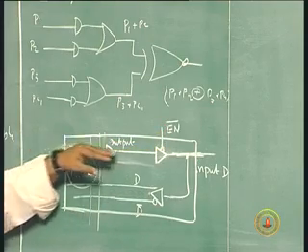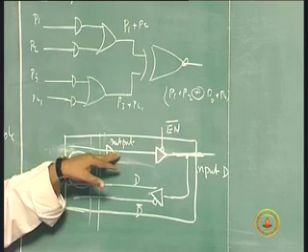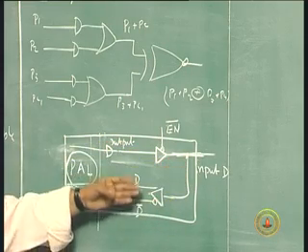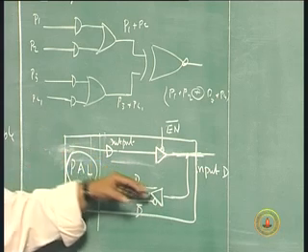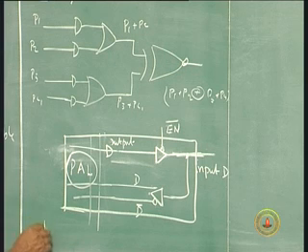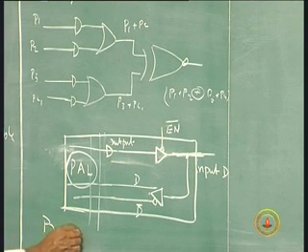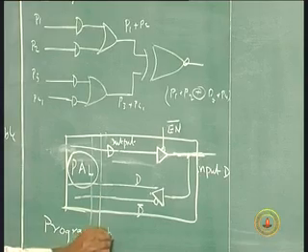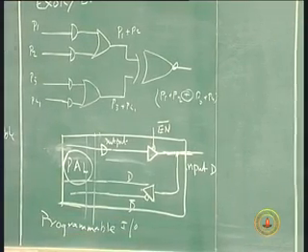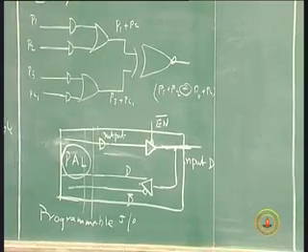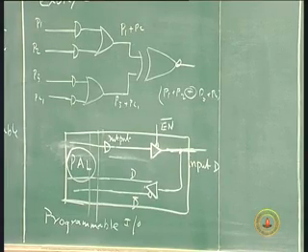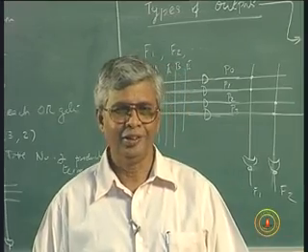Actually, this AND gate is not available as output, this OR gate or whatever, this is an OR function, it is not available. So, I take this and use it as an input with this one complement and all that, and then it will be also used in my synthesis. This is my programmable I/O. So, you cannot have both, of course. Some of them have to be programmable. If you want to use a device of this choice, you have to choose one with that feature. And once you have 16, 8 and 8, I cannot have 16 inputs and 8 outputs, that is not possible.